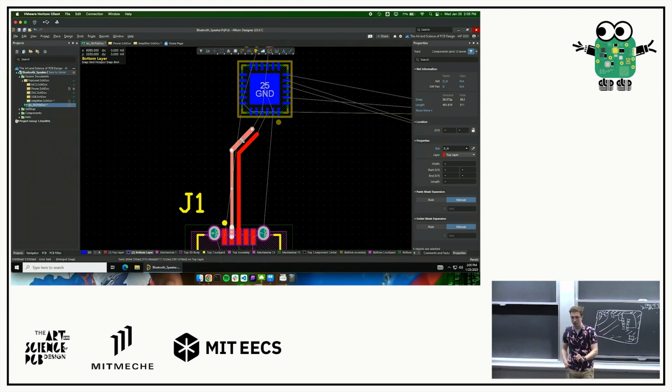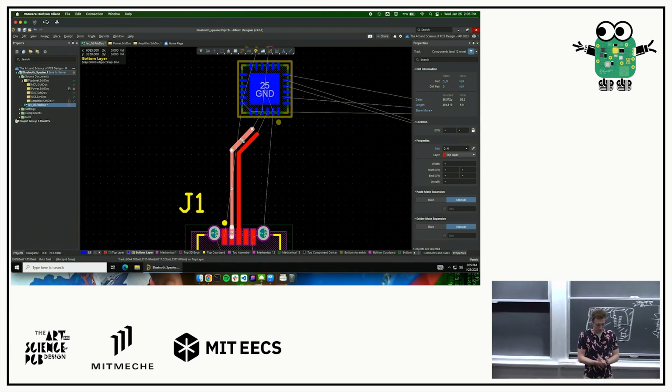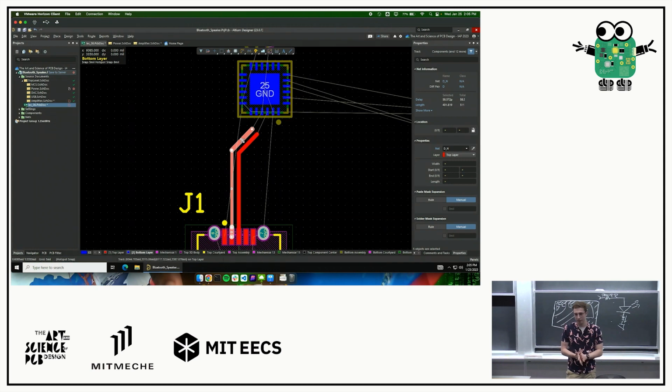Cool. Just real quick to add to the two places I think you would use them really close to each other, especially because board cost goes up quite significantly with board area. So when you're manufacturing at scale, packing those components as tight together is very useful. And then what you would do, with a power plane and ground plane, is have a via basically as close to that ground pin as possible. Just send the ground straight down to the plane.